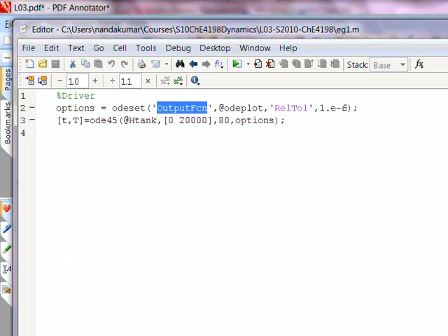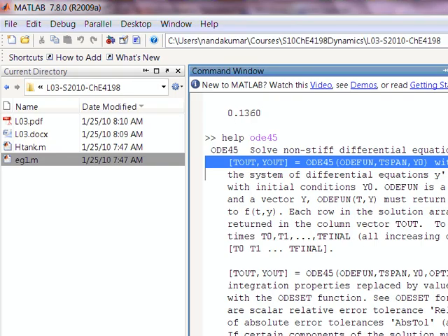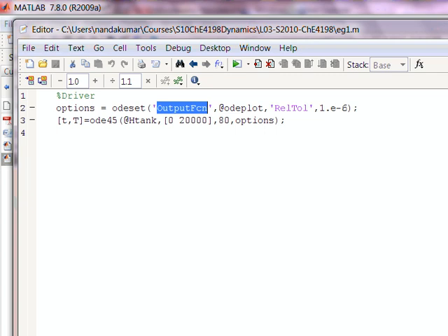Good question. I already have in my workspace a variable called T. So what will this do is your question, right? No, it will just overwrite it. So whatever comes out, that's a good question. Whenever something is appearing on the left-hand side of the equal sign, it's an assignment. So it's going to assign to that lowercase t and uppercase T the values returned by ODE45. If your workspace already had a t defined, it will be lost. Okay? Any other questions?